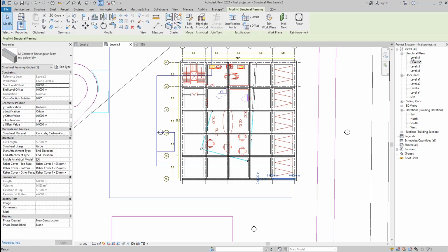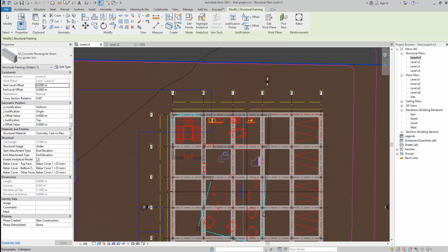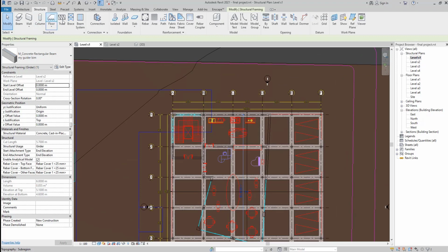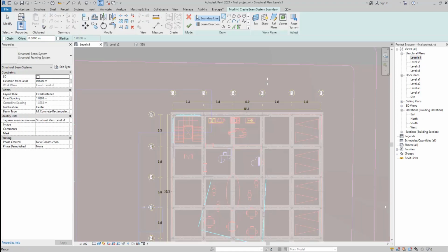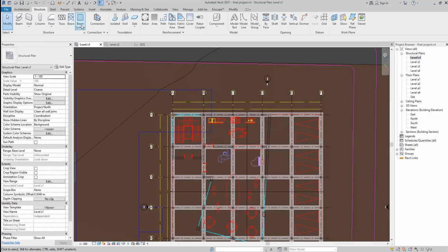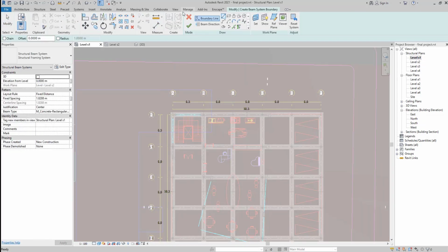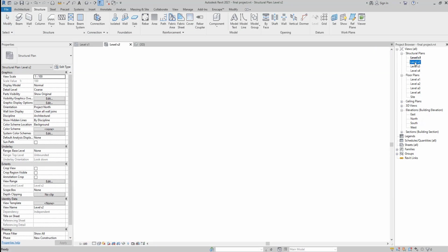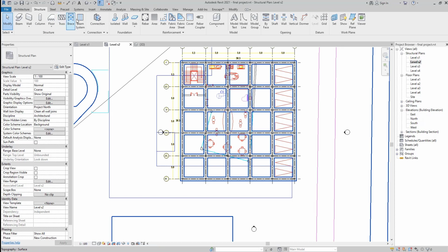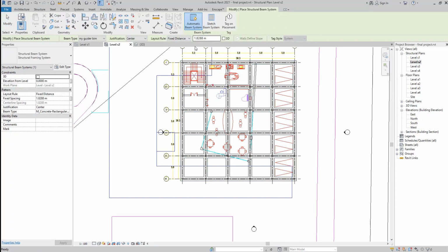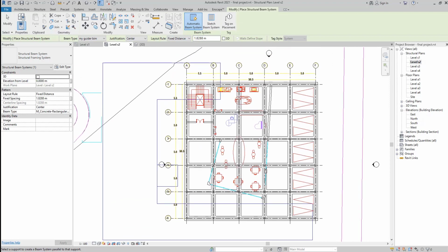After that, the next step is to create our joist beam. We will go to level S1 again, and we are going to structure and beam system. If this error happened for you by opening your beam system without even having an option to choose between your automatic and your sketching, it means that you are not in the right level. You need to go to the level S2, open your beam system, because we are going to have two beam system drafting situations. First is the automatic beam system, and the other one is the sketch beam system.